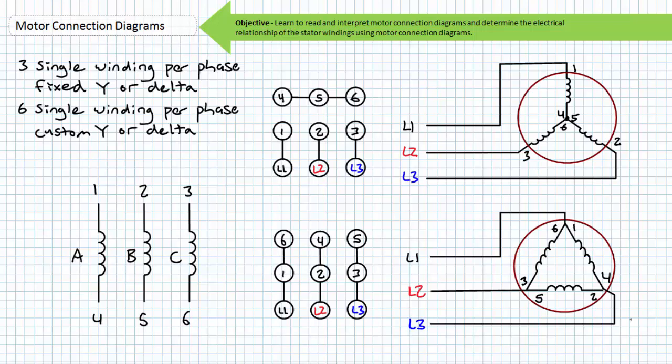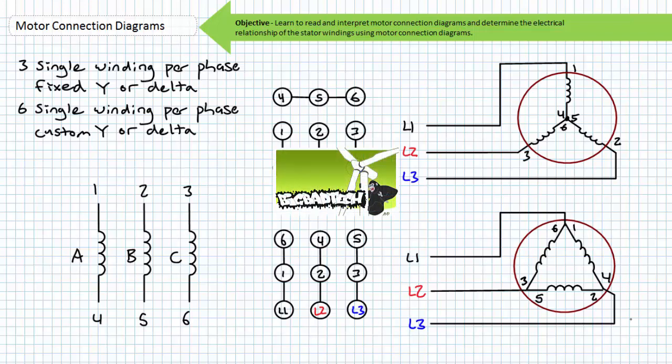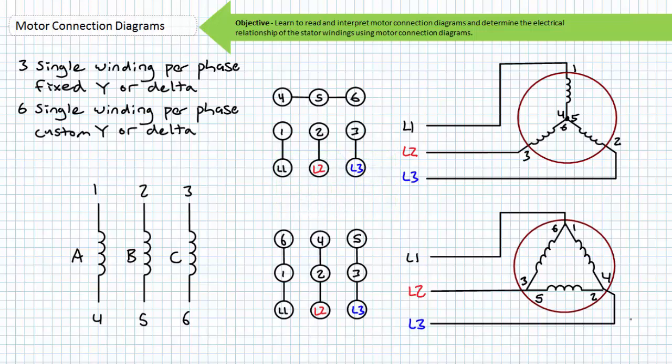Once the motor has achieved a given speed, counter-electromotive force, sometimes known as CEMF, a concept discussed in the electromagnetic interaction lecture, will be greater, and then full line-to-line voltage can then be applied in a delta configuration. The stage application of voltage to the motor windings ensures inrush current doesn't place an unnecessary burden on the electrical supply system. We'll discuss this and other methods of reducing inrush current in later lectures.